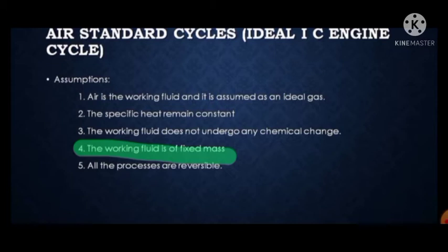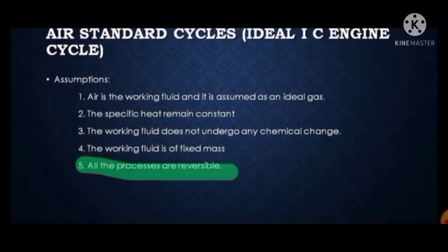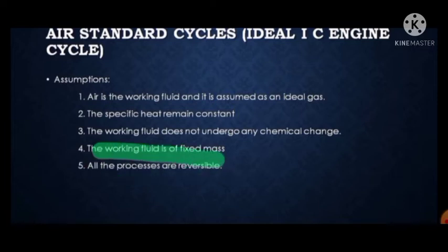Fifth, all the processes are reversible, whether it is a constant volume process, reversible adiabatic process, or constant pressure process. So these are the five most important assumptions of the IC engine. These assumptions are asked in interviews. They ask that the IC engine is an open system, still you are using a closed system. So you have to say that the working fluid is of fixed mass, and we are assuming it is a closed system. We are assuming air is the working fluid and it is an ideal gas.